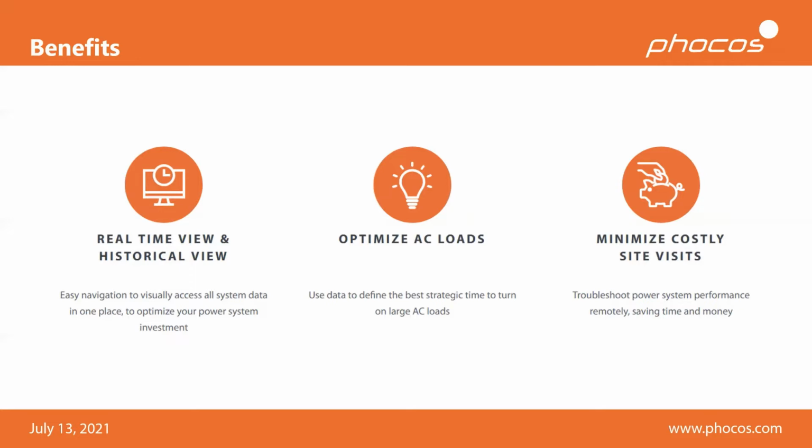So all of these loads you will tend to want to run during the day when you are likely to have excess energy left over, and you want to avoid running them in the night or in the morning when essentially your batteries are probably nearing depletion. They're being discharged throughout the night. So you want to make sure that you use the batteries only for your bulk loads, your main loads, but not those big, large loads that tend to discharge your battery very quickly.